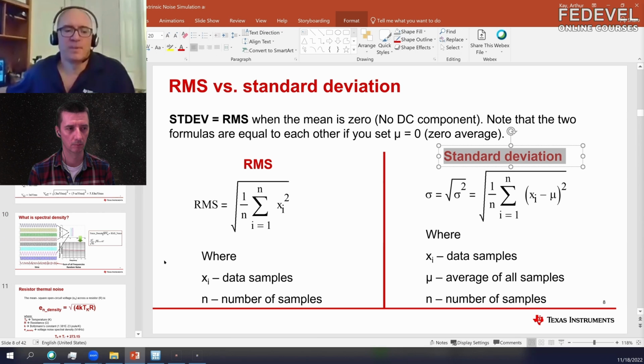If you collect noise through whatever means, probably the easiest way to find out its RMS value is to just use Excel and find the standard deviation. So you would collect some measurement data in time, put these voltages into the Excel table, use this equation, and you would get how much noise you have, RMS. Yes, STDEV, standard deviation.